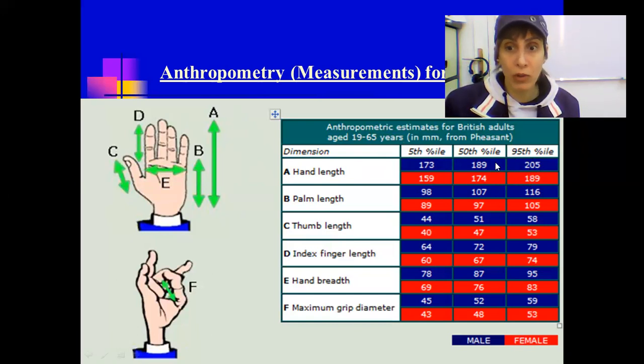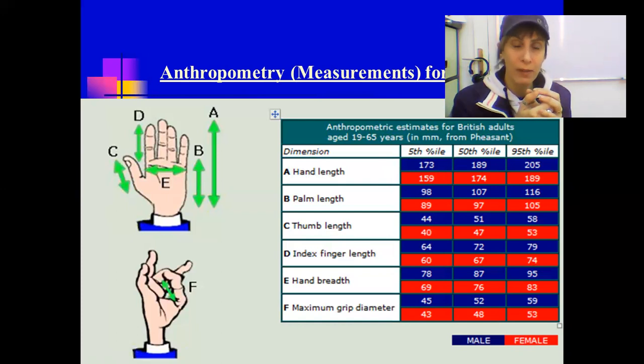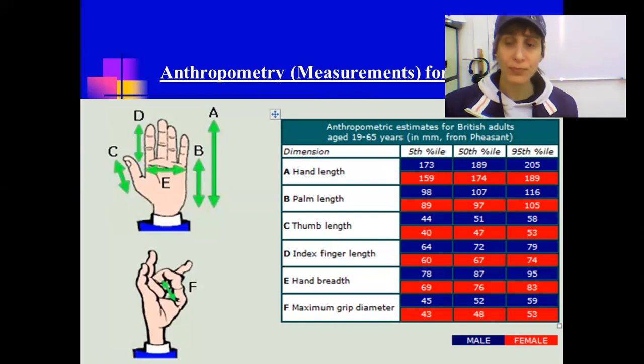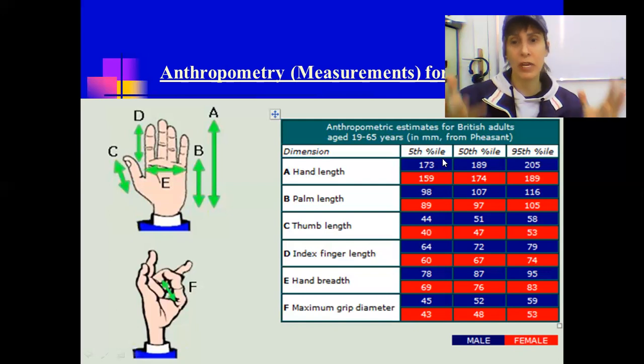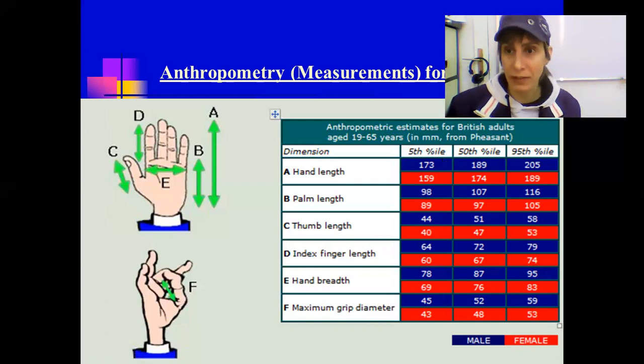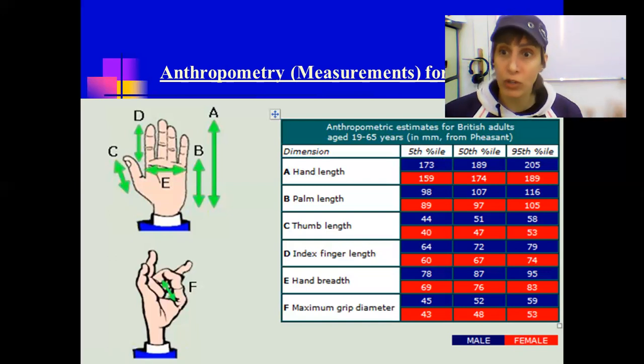So for hand tools, sometimes you have to use these measurements, sometimes you have to use these to fit all of these, but it depends on really what you are designing. Sometimes this is the most correct measurement to use, but then maybe the small people will have some issue. It will be a little bit too big for them. So sometimes you have to design for both genders separately, because measurement-wise, it will not fit comfortably. So a lot of decisions to take before you design something.